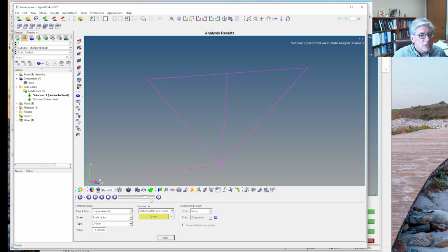you'll see that it doesn't really do much. That's because the displacements are typically very small. They're nowhere near the order of 4 feet. So you usually want to scale them. You can see there's a scaling factor here. Right now it's set to 1. If you set it to something like 250 times, now I can see something that makes sense.